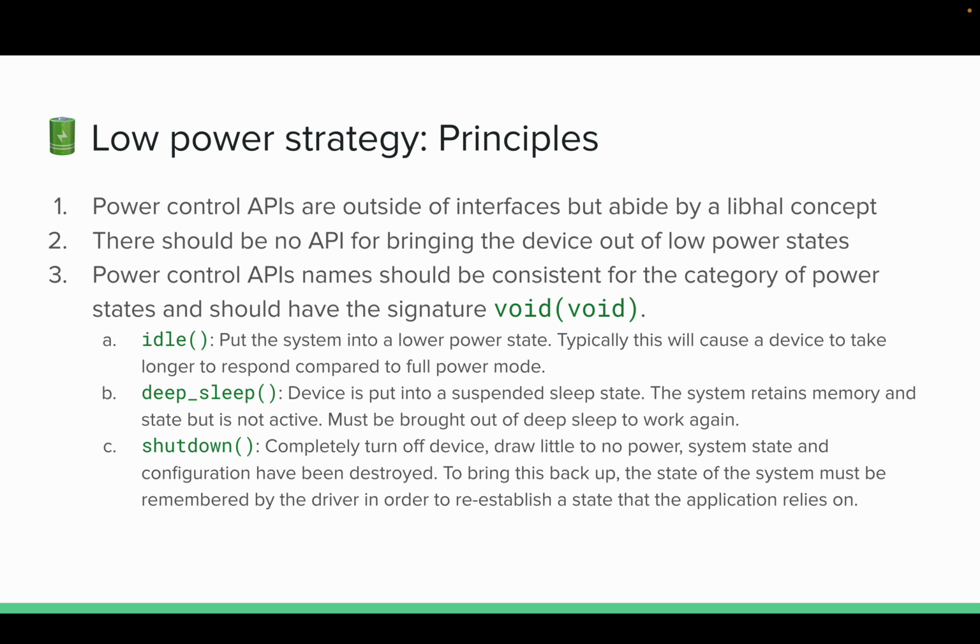The idea here is that it takes even longer for these things to happen. So deep sleep, if you're going to use it, you have to tune your design, your application with that in mind. Shut down completely turns off the device, and it draws little to no power is the idea. But in any configuration, the state that you had before is completely destroyed. To bring this back up, the state of the system must be remembered by the driver in order to reestablish a state that the application relies on.